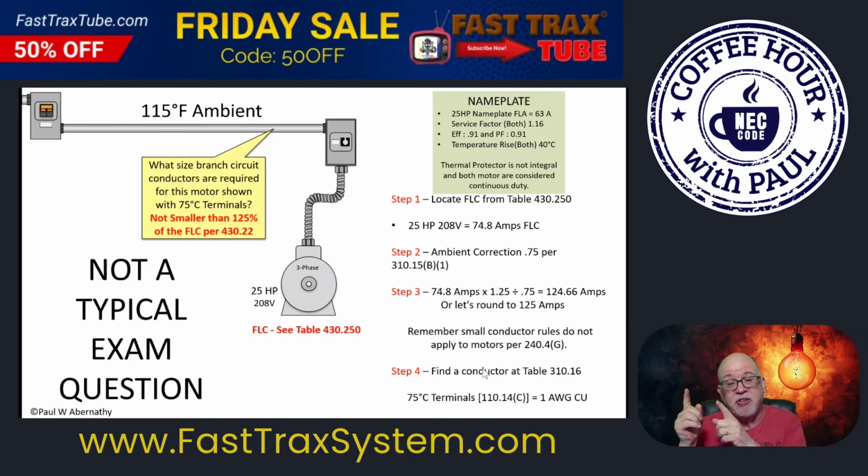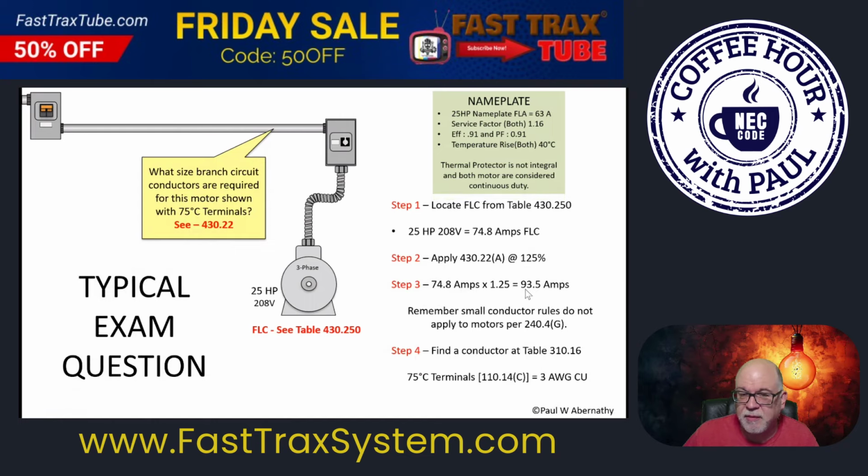And we can use multiplication to verify that by simply taking the 130 and multiplying it by 0.75, and you'll see that we have a conductor that is, I believe it was 97.5, that easily can handle the requirement, the FLC at 125%. We were okay for that application, all right? Does it make sense? 97.5 is greater than 93.5. That conductor is perfectly fine, but we had to jump up to a 1 gauge to make that happen.